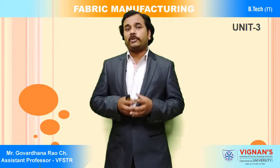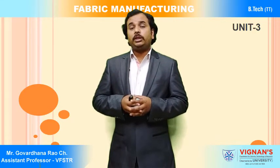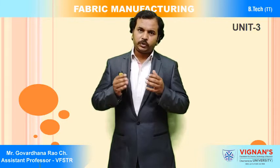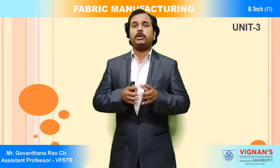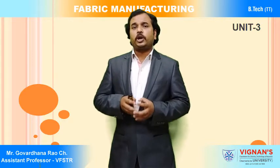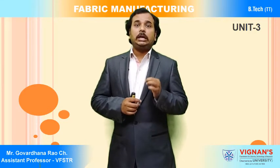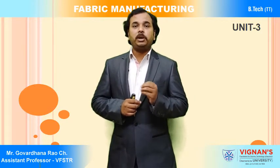If the number of colors is different, it will take even more time. That is why, if the yarn quality or fabric quality is the same, we go for the knotting operation, so we can eliminate the time consumed by the drawing in and denting process. As I told in earlier classes, the knotting machine can knot 500 to 600 ends per minute.